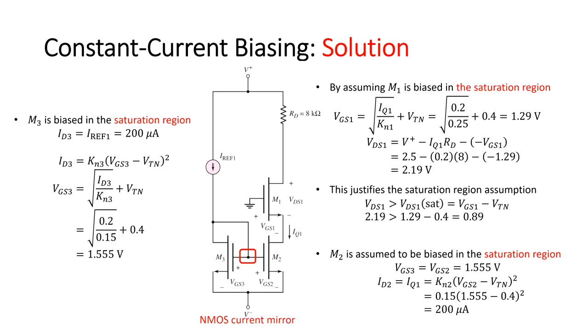As you realize, the current IQ1 is equal to the independent current source. In other words, since the parameters of the transistors M2 and M3 are equal, they reflect or mirror the reference current value. However, by changing the transistor parameters, we can adjust the reflected current value.